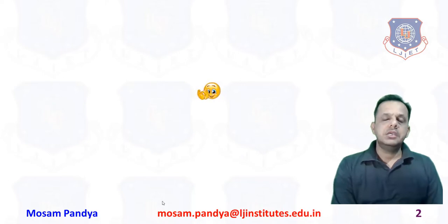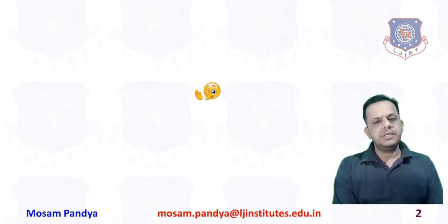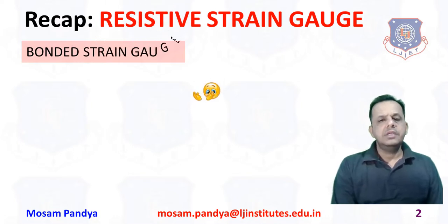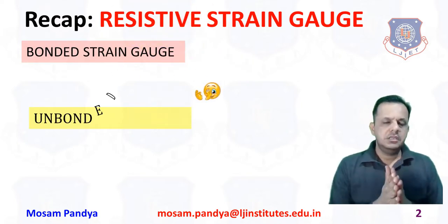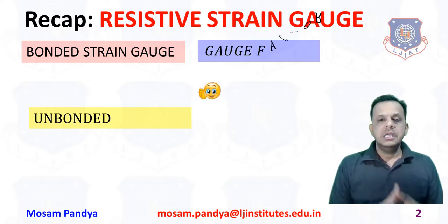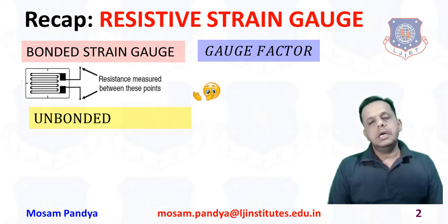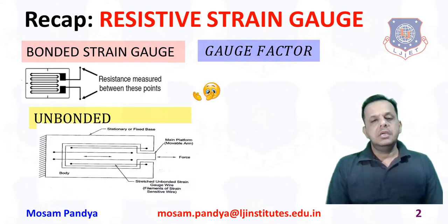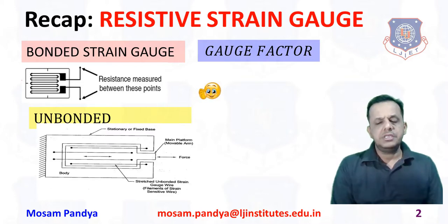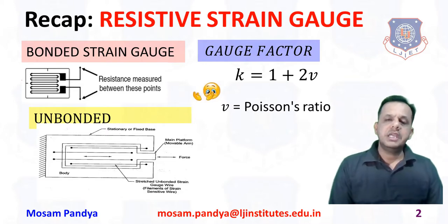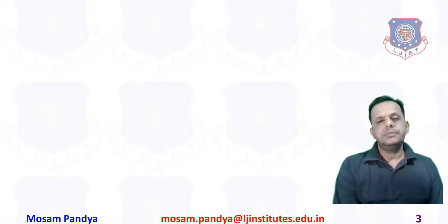Before that, let us recap very quickly what we did in the previous session, and that was all about resistive strain gauge, where we had bonded strain gauge, unbonded strain gauge, and gauge factor. For bonded and unbonded types, we just saw the simple configuration, and we basically focused on the derivation of gauge factor. You must remember that K is equal to 1 plus 2 mu. So let us go ahead further.